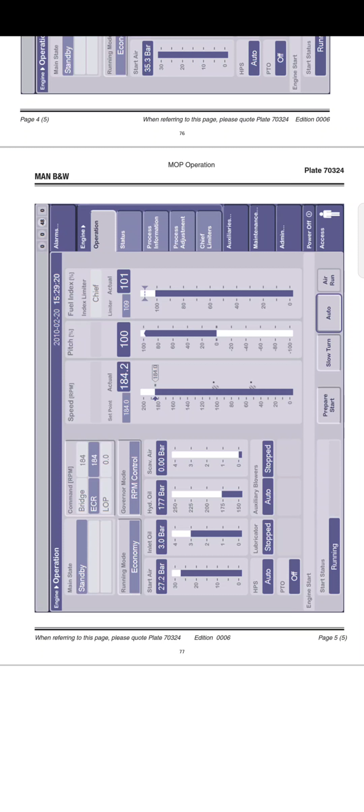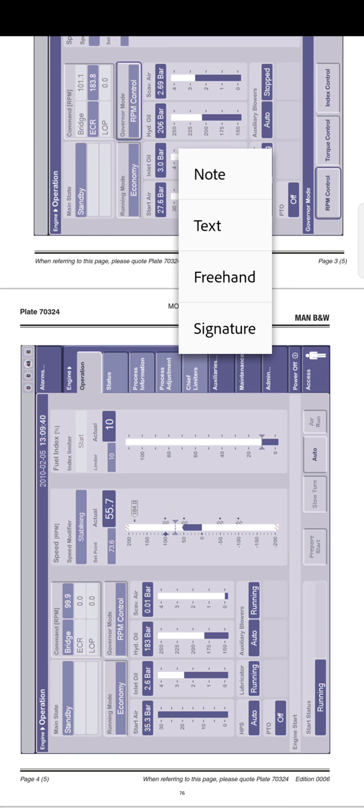Now the main state. The main state field contains 3 status fields indicating the current state, sub telegraph command states, and the states of the engine. The background colors of the graphics are blue for the normal state, yellow for warning state, red for alarm state, and gray or dimmed for not in use. The top field indicates finish with engine, standby, or at sea. It is the main state; here you can see standby. There can be only 3 states of the engine: finish with engine, standby, or at sea. The middle field indicates the states of the engine.